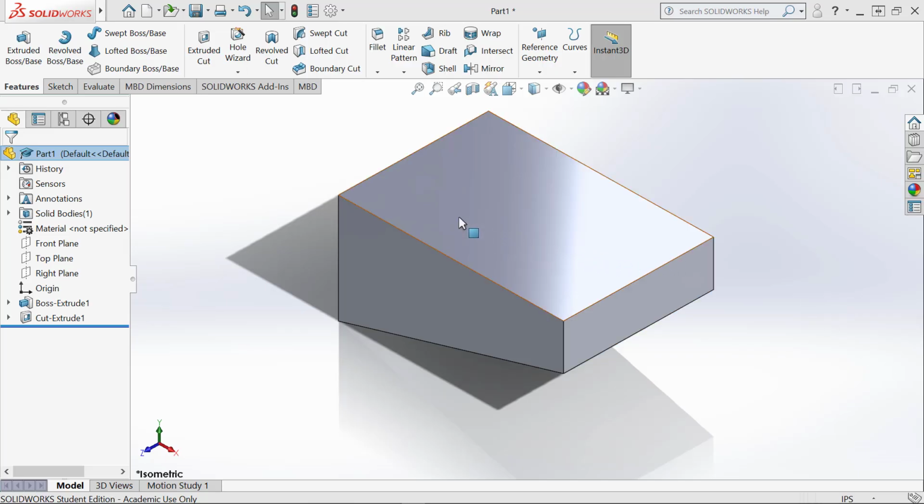So I'm going to fill the top surface of this body with a matrix of holes, n by n, using the linear pattern feature. In order to create a linear pattern feature, you need a seed feature. So you need at least one hole, and the location of the hole has to be one of the four corners. So I'm going to create a hole in this corner.